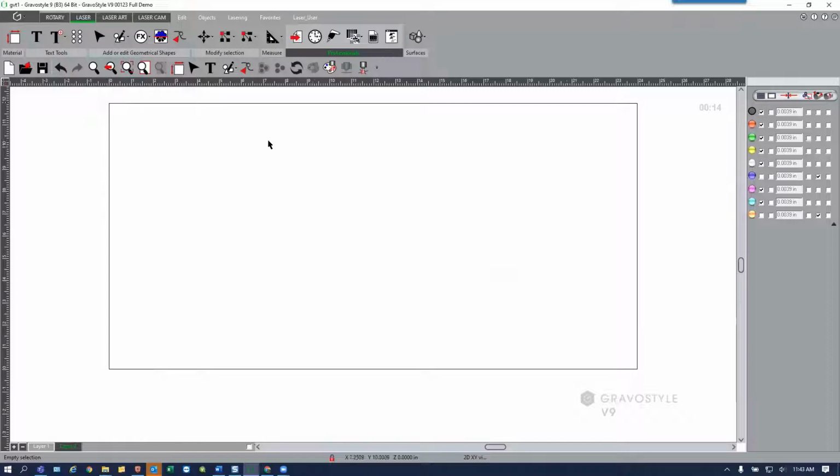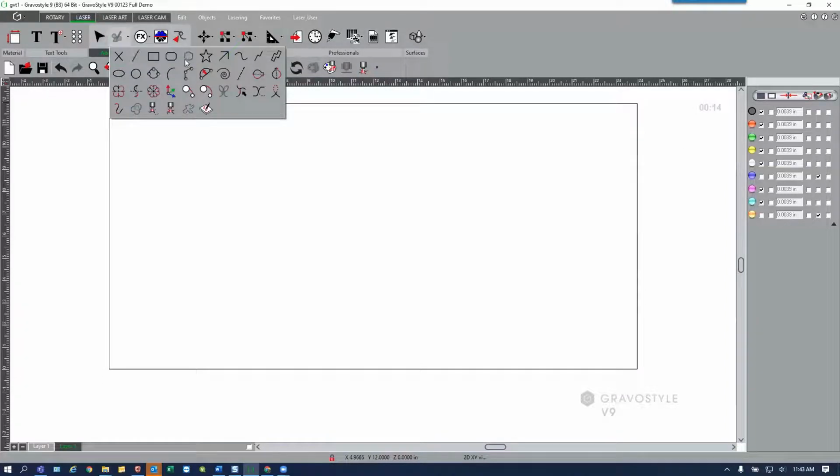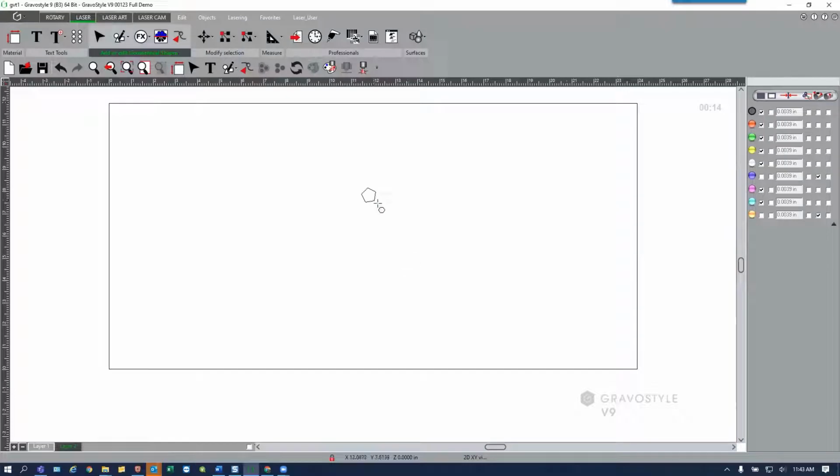Okay, over to the right, we see the laser properties toolbar or laser parameters toolbar. This allows us to assign a contour that may be on the screen by color. So with a contour selected, I can come over and reassign that to be a different color now. And if I don't want that to be filled text or filled shapes, then I can take the checkbox away and tell it to just do that as a raster line instead of raster fill. And here I can define how wide that line should be. So I can make the lines heavier so that they raster engrave.